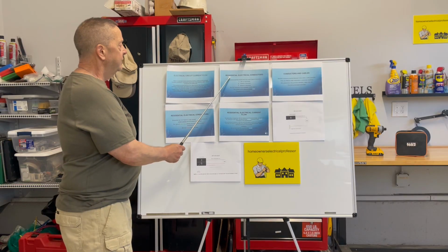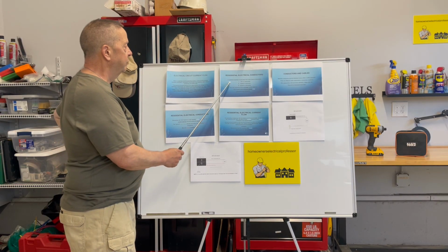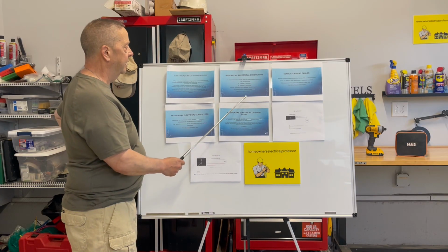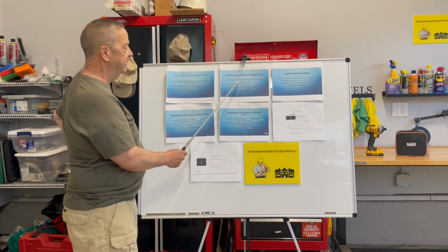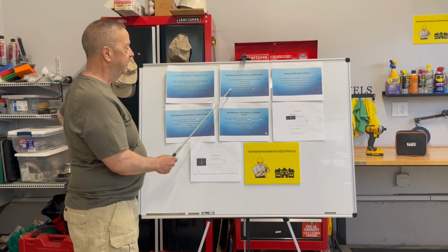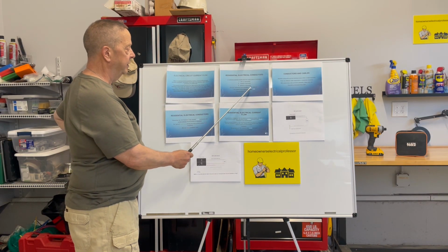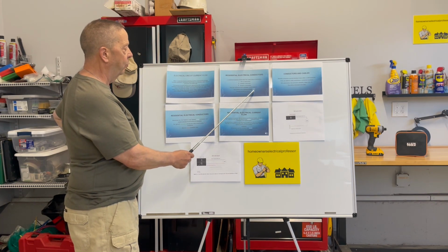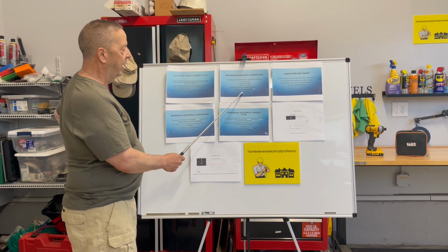In residential electrical circuits, there are three basic types of conductors: the hot or the ungrounded, the neutral or the grounded, and the ground or the grounding. The hot conductors will be insulated, usually black or red. The neutral will be insulated, always white, and the ground wire may be bare or it may be green.